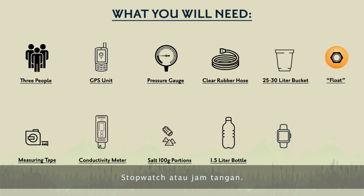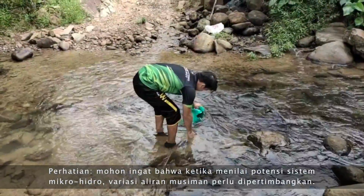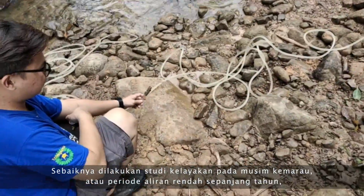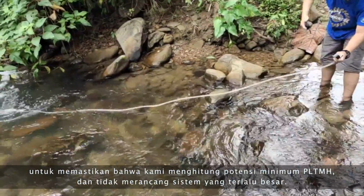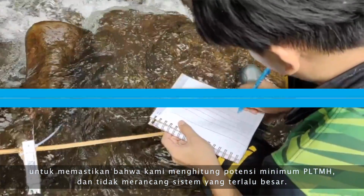and a stopwatch. Finally, it is also important to remember that when assessing the potential of a microhydro system, seasonal variations in flow need to be considered. It is best to conduct a feasibility study during dry season or low flow periods throughout the year, to ensure that we calculate the minimum potential of the microhydro system and do not design a system that is too large.